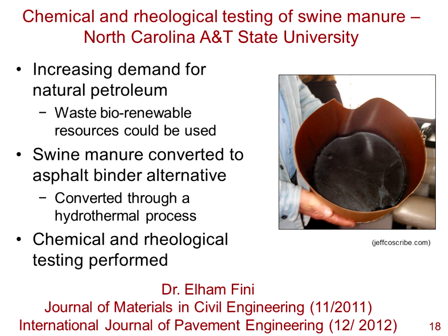So again, we're not taking anything away from the food stream, we're just looking at current waste streams that may be used for other areas, but the use of biobinders could maybe be a better and more efficient use of this waste. And what they did is they used a hydrothermal process to convert swine manure to an asphalt binder alternative, and they tested some chemical and rheological characteristics of that.